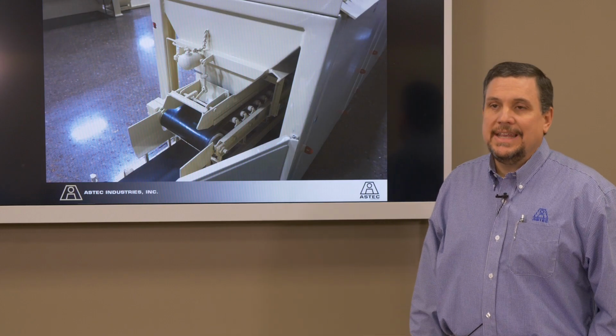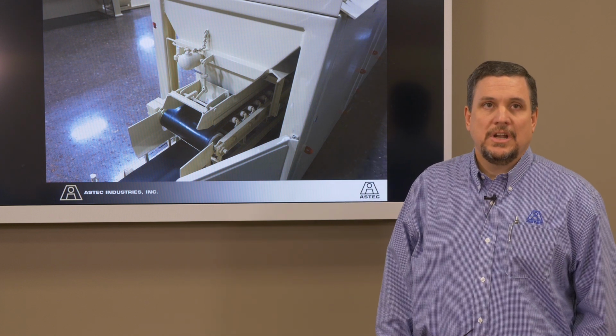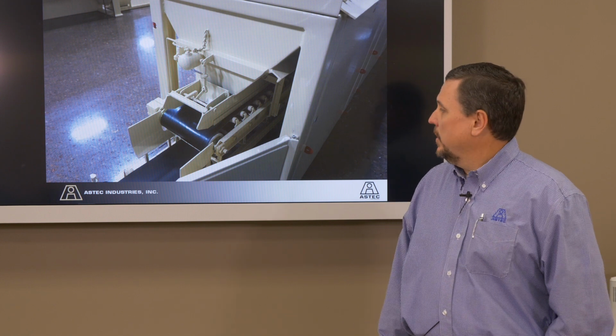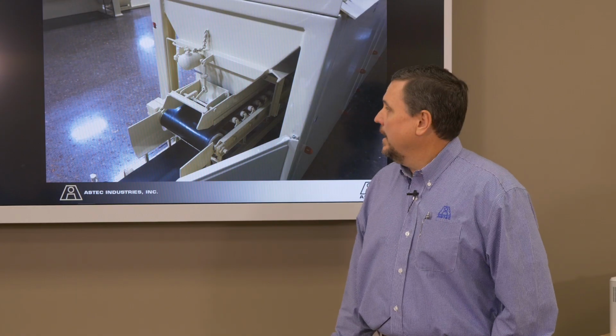Another thing that you will see is that the conveying belt at the bottom of that feeder is much wider. Usually it's going to be a 36-inch belt, and you also still have the adjustable gate. Again, it's all there to allow that RAP to flow more freely.